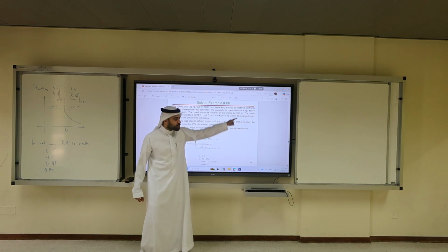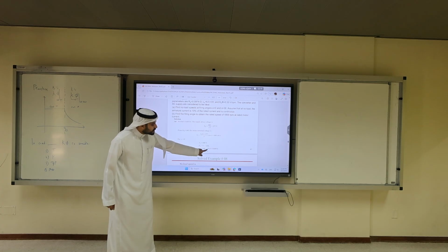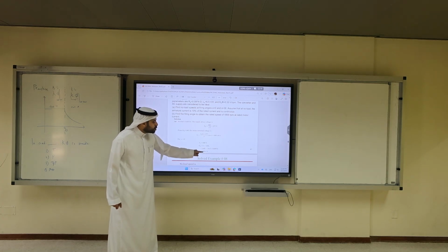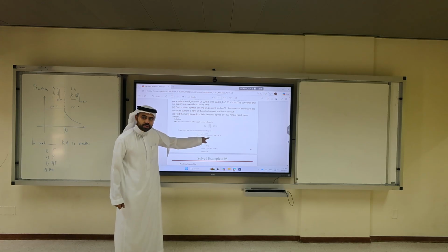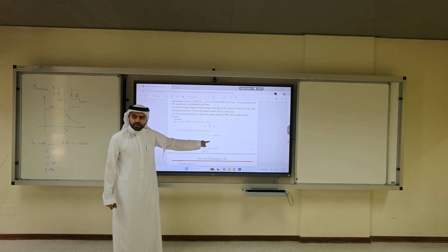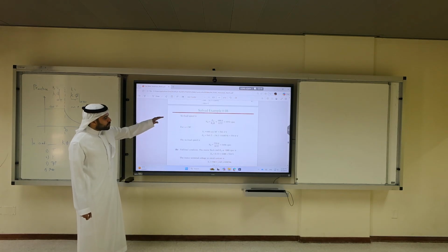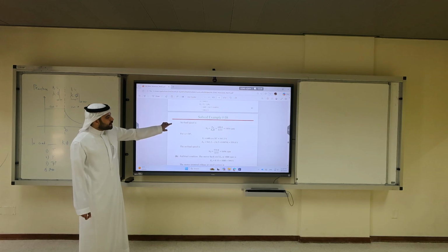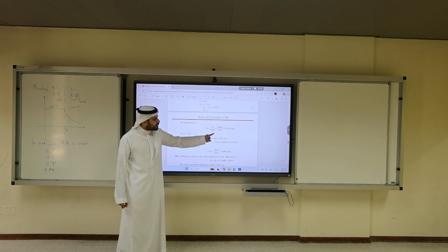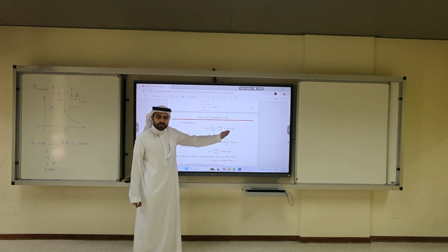That's why we have here EA equal VT minus 16.5 times RA, then you get the 646.6. You plug in VT, of course, one time at cosine 0, one time at cosine 30. Okay? So if you do it for the no-load speed, again we're using EA over the constant that has a unit of V over RPM. It's 646 over 0.3, which is 1959 RPM.